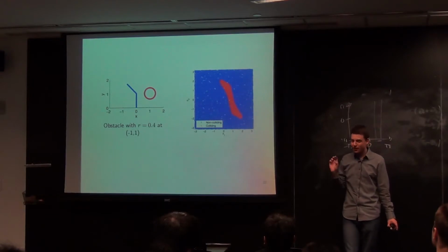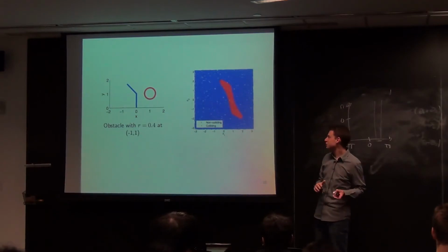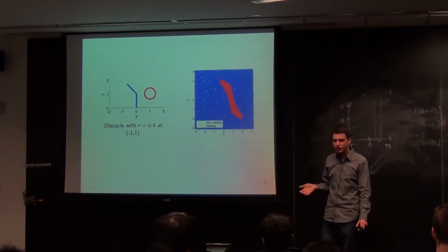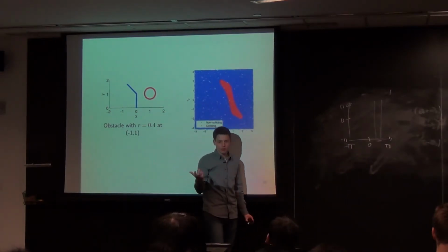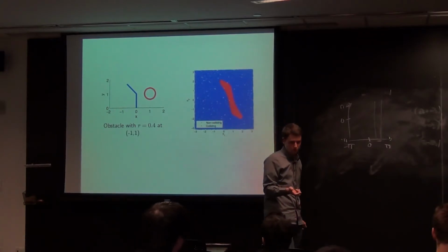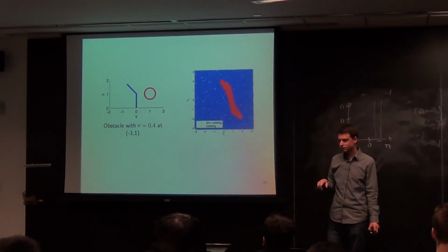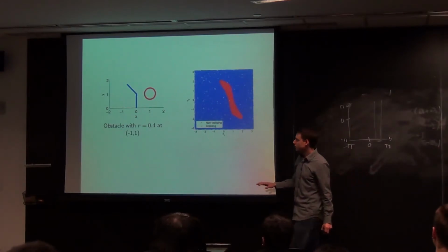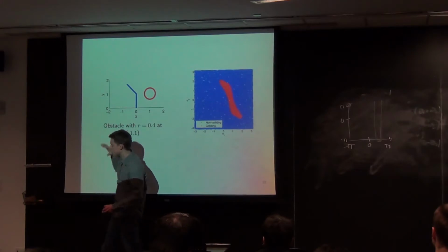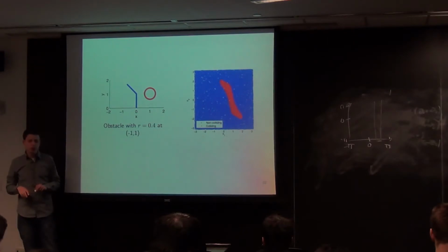So there are all these points where there are transitions between something that can always collide in a certain region and not collide in a certain region, and it's very non-intuitive. And this is about as simple as you could get. It's a 2-link robot with one circular obstacle. Even when you have square obstacles, this becomes a lot nastier. So we typically don't want to try to do manipulations at the level of the precise geometric manifolds we're talking about here. And this motivates a lot of work in what we'll talk about for the rest of this lecture, which are called sample-based planning techniques.